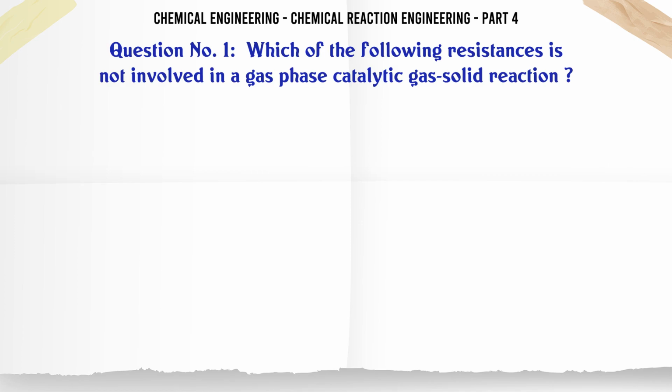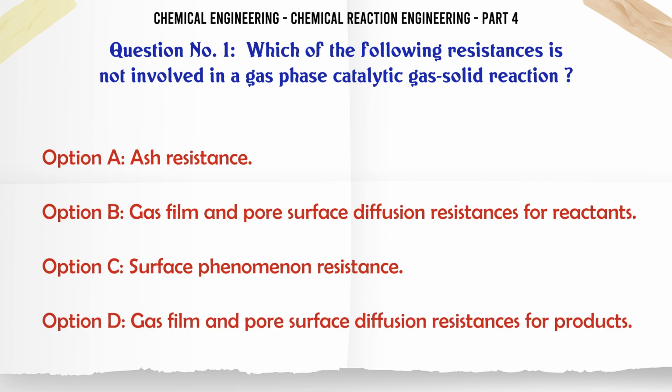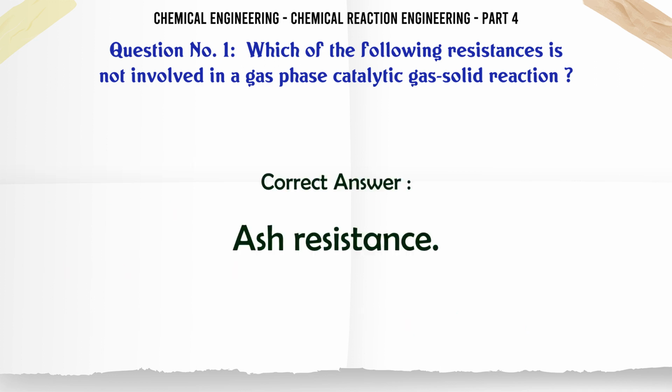Which of the following resistances is not involved in a gas phase catalytic gas-solid reaction? A. Ash resistance. B. Gas film and pore surface diffusion resistances for reactants. C. Surface phenomenon resistance. D. Gas film and pore surface diffusion resistances for products. The correct answer is ash resistance.